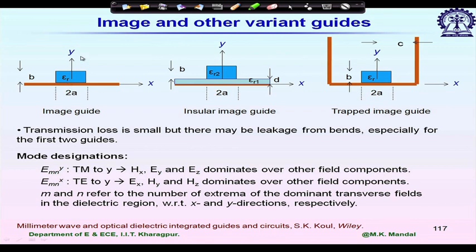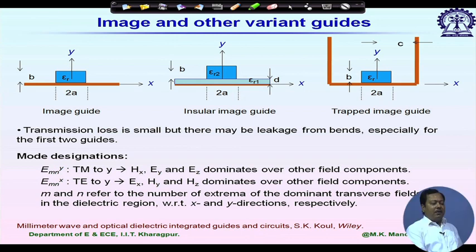propagation. Do you remember the surface wave TM case? Similar thing. In TM mode surface wave generation, we also have the normal component of electric field and also in the direction of propagation. So similar to that, here also the dominant components are EY and EZ.